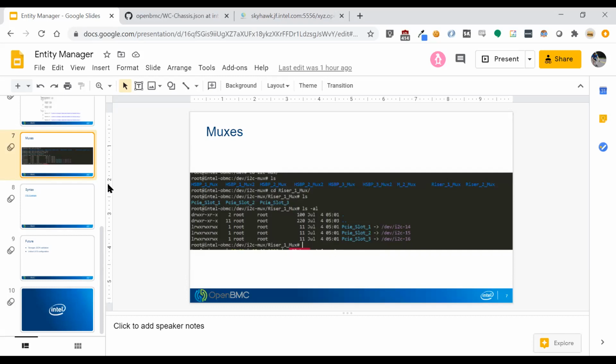So for our systems, normally the things that are discoverable have something behind the mux so we can tell that it's there. And so at that point, we've been basically just using another FRU probe after that. Now that the mux is there, Entity Manager can see behind the mux, and it'll scan behind the mux and then add something. There isn't any syntax today to say behind this mux, add this card. So that's not supported today.